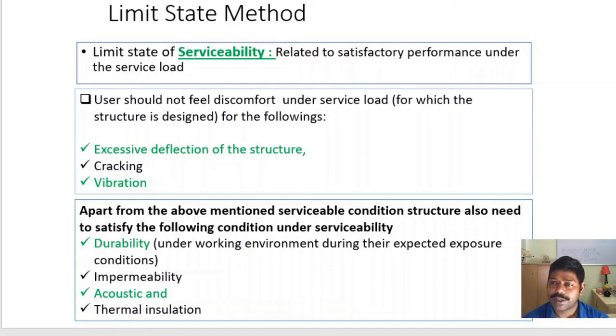In case of impermeability, you should take proper care while you construct the top floor or the floor near the bathroom or washroom. While constructing the top floor, if you pour more concrete at one time, there will be a high chance of shrinkage cracks. You should take proper care while casting the floor. There should be proper curing, you should maintain the water cement ratio, and you should also use some admixtures to reduce the shrinkage.